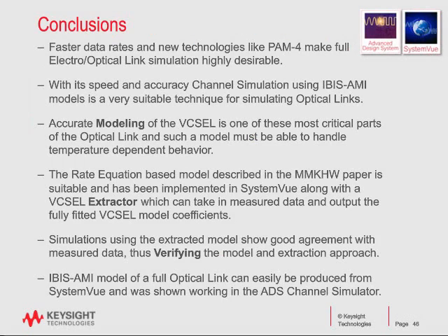So that's it for the presentation. I'll just run to the conclusion here. Faster data rates, new technologies like the PAM4 I just showed make full electro-optical link simulation at the PHY level highly desirable, so that you can see as things are changing, as you're being challenged over data rates and modulation formats, what's going on in your system. Channel simulation provides a great vehicle for doing that because it's fast and it can use the IBIS-AMI model, which we've shown we build optical links.